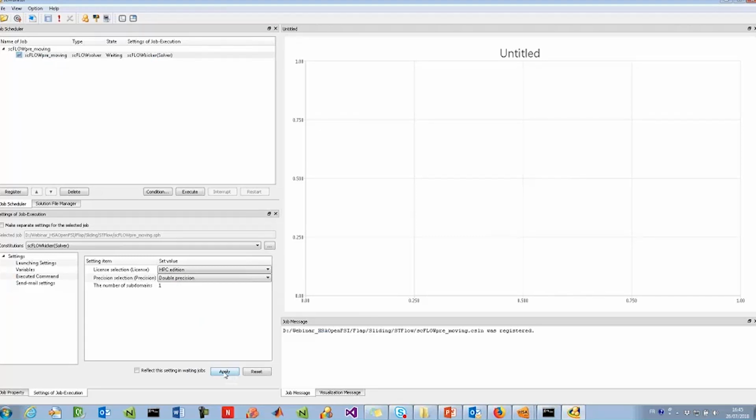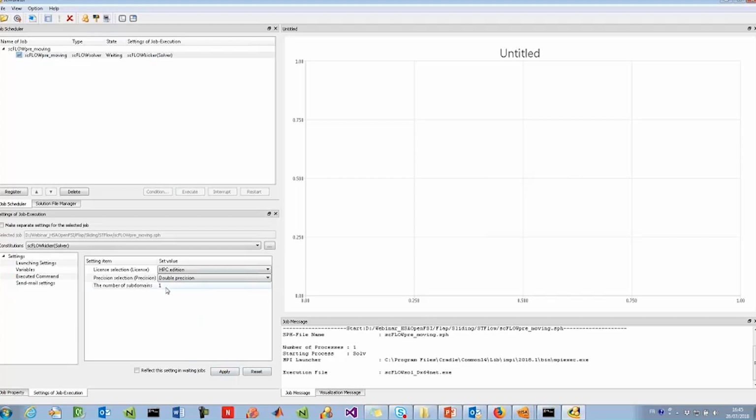So soon the MPI will be available, so we can run SC-flow in parallel. Since we're using just one core, in this case it will be a little bit less fast than the case in which we use SCTetra, but you can see that it's still running fast. And on top of it, when we use a polyhedral mesh, the number of degrees of freedom increases, because with a polyhedral mesh we have more faces and more nodes per face, and so the number of nodes increases a lot.